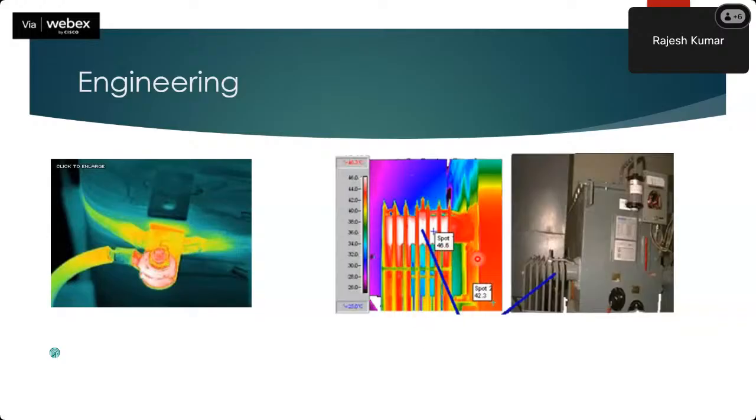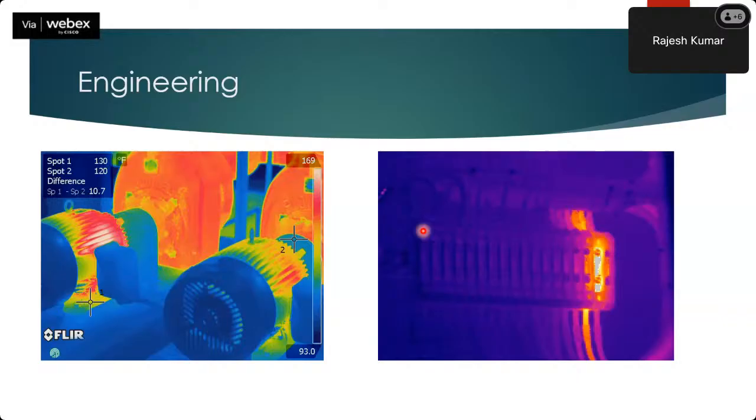What people are doing now is taking thermal camera images, and from the images they try to predict what the temperature is at a particular point. Why? Because sensors have limitations. Take this case of a motor. You can say this one is inside the motor, where there are windings which are rotating. So what is the temperature at a winding? These are images taken from thermal cameras. Putting a sensor inside a motor which rotates at a very high speed creates a problem and puts a question on durability and all those things.